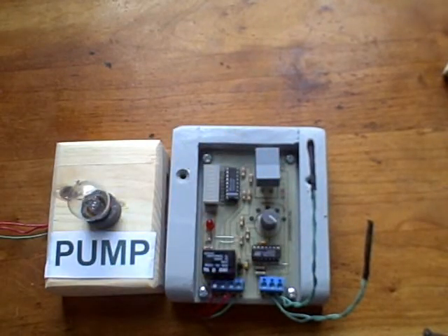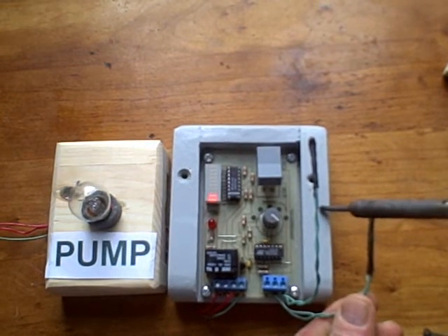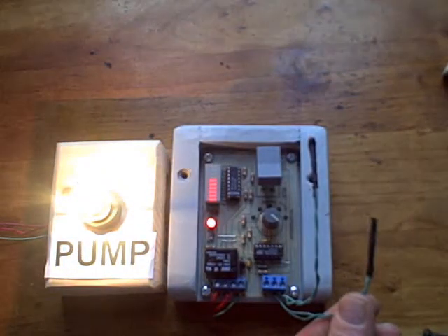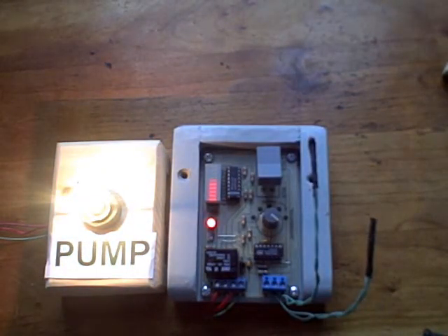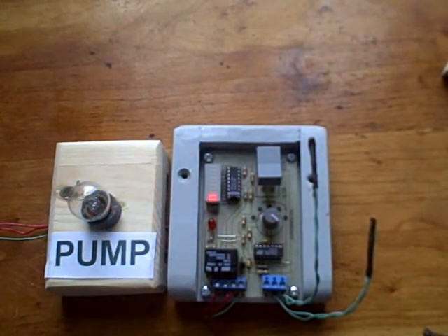The next thing we want to do, we turn the differential all the way up, so it's going to take quite a bit of heat in order to turn the pump on. Let's see how hot it has to get. We're already up to, alright, the temperature now is about 130 degrees, and the storage temperature was probably about 60 degrees, so maybe 60 degrees for the differential to turn the pump on at the maximum setting.